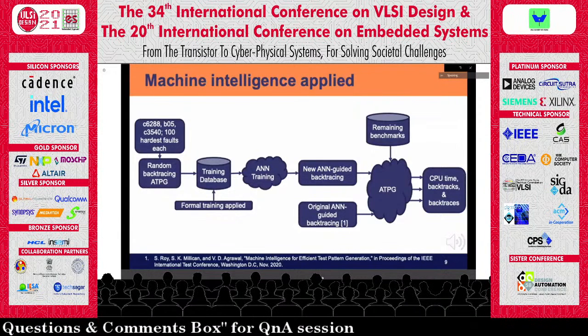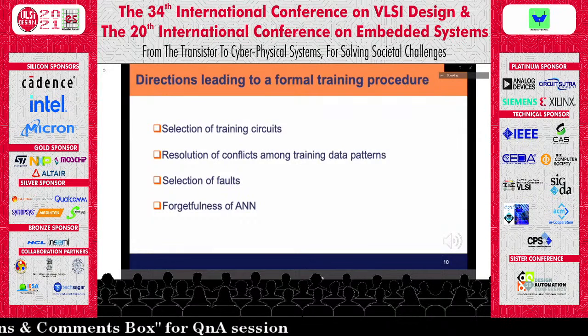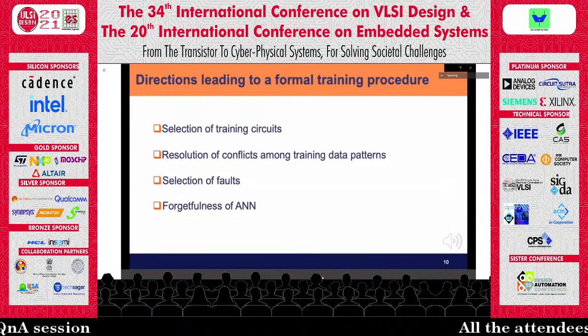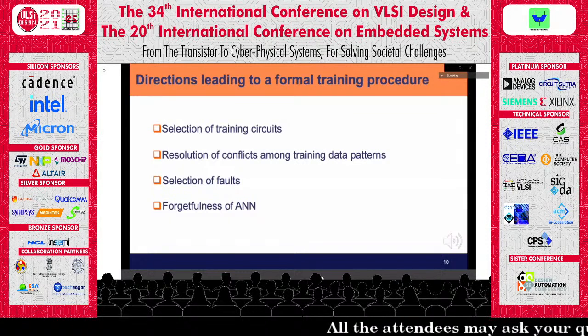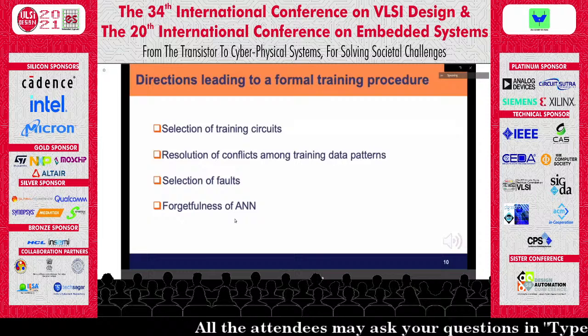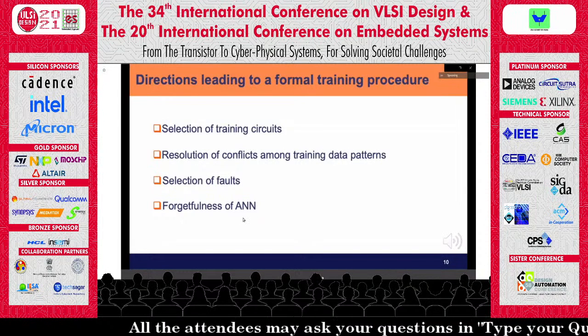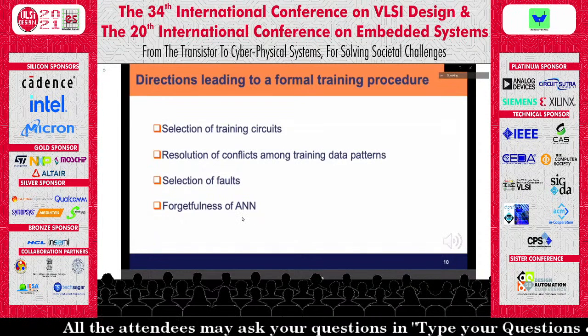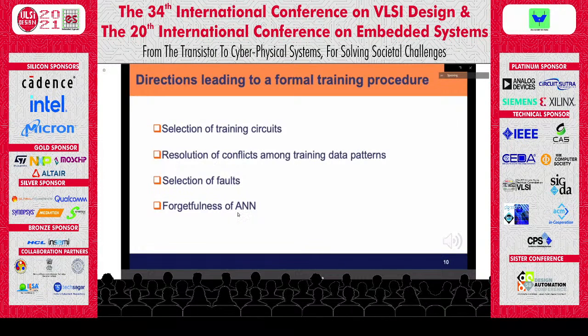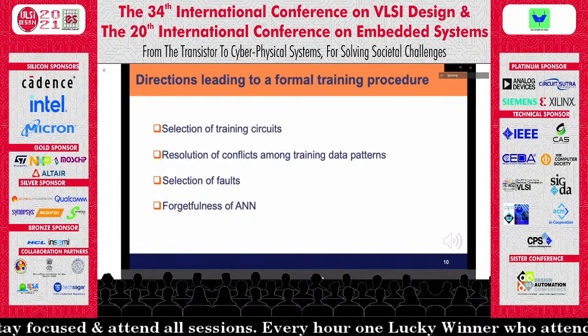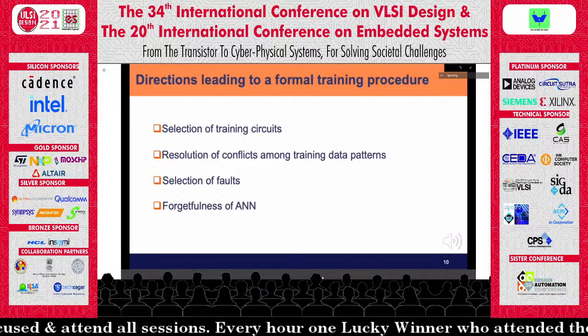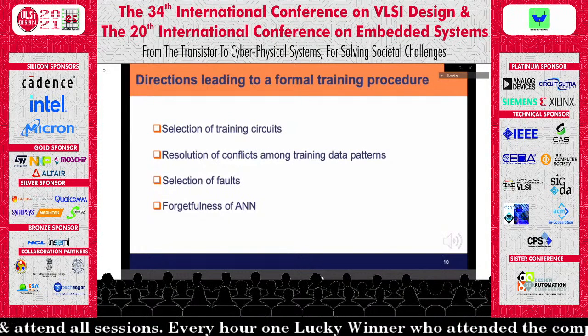We believe remedying the outliers just mentioned a few slides before requires addressing several aspects of the ANN training procedure. Our investigation led us to the following observations. Firstly, the ANN was trained with ATPG data from high-depth circuits. Since C3540 causes worry, I retrained the ANN with just C3540, but still the ATPG performance of this circuit did not improve. Therefore, I retained the 3 high-depth circuits for training.